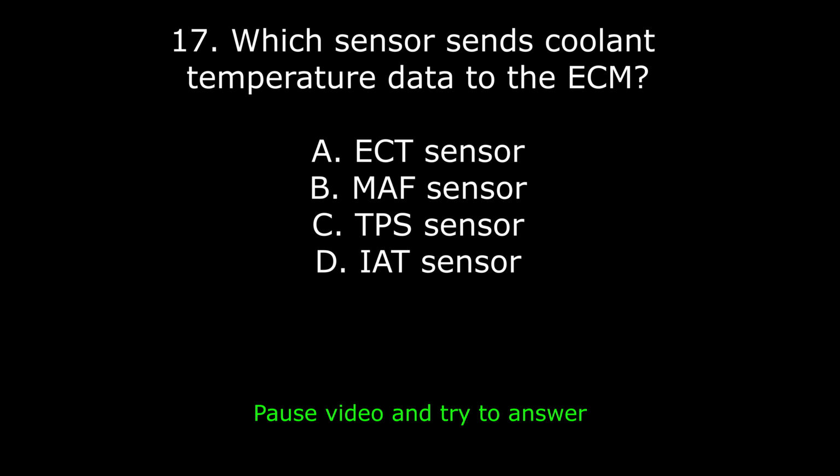22. When measuring resistance in a circuit, the meter should be connected: A. In series with circuit power on. B. In parallel with circuit power off. C. In series with circuit power off. D. To the battery only. Answer: B. In parallel with circuit power off. Explanation: resistance testing requires circuit de-energized and meter connected across component.